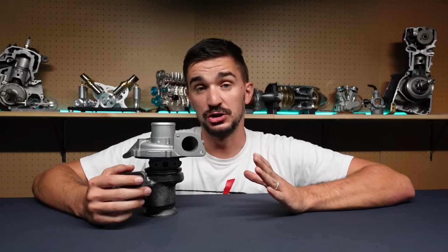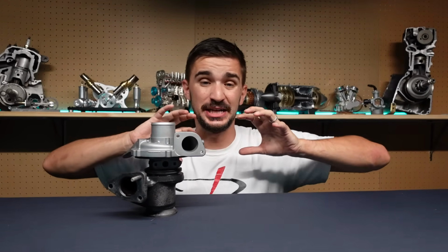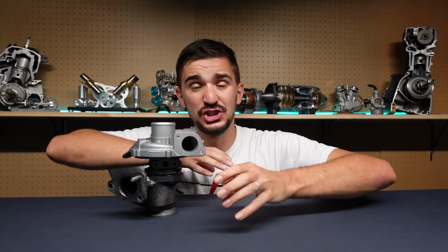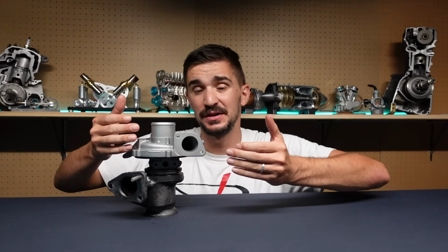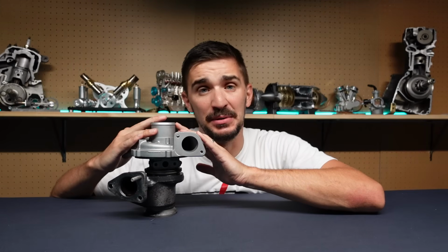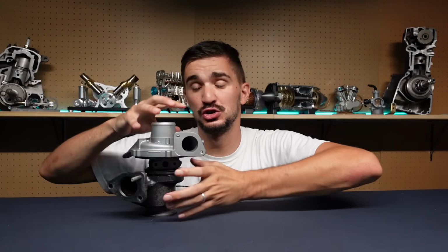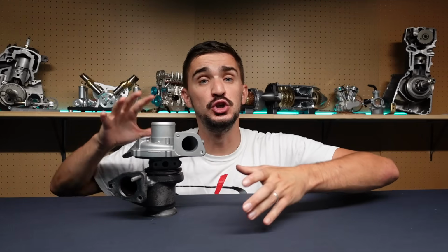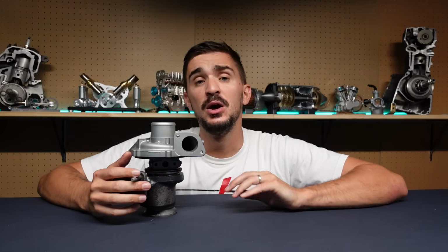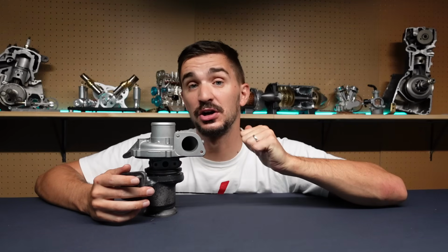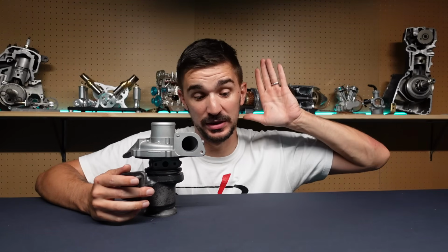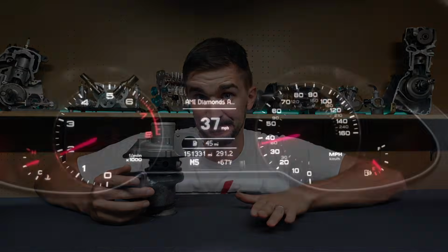Surge or compressor surge occurs whenever the turbo is trying to stuff more air into the engine than the engine can swallow. This causes reverse pressure waves coming from the intake side of the engine back to the turbo, and it can damage the turbo. The easiest way to cause compressor surge is to install a turbocharger that is simply too big for the engine. We have to distinguish between two kinds of compressor surge. The first one occurs when the engine is under load, so when the throttle is fully pressed.